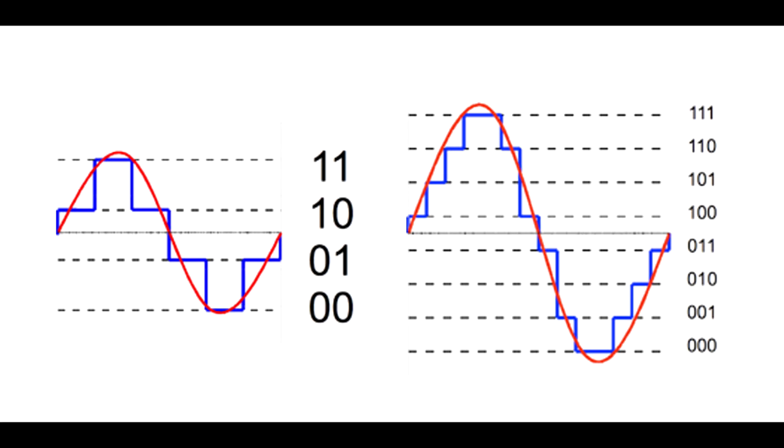Quantization is the process of converting data from a larger set to a smaller set. Typically, this occurs in analog to digital converters when they take continuous real-time data and turn it into a series of discrete values for given times. This allows a previously uncountable data source to be made into a countable and thus usable one.